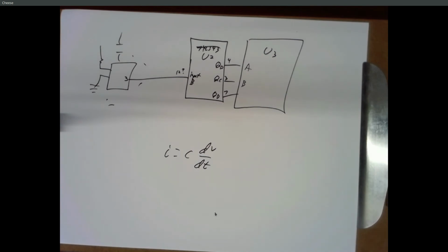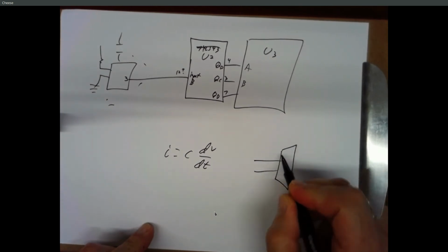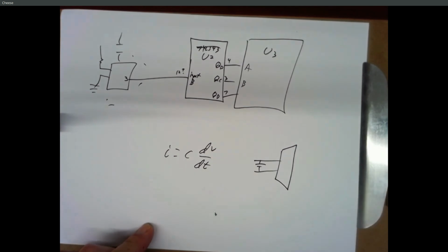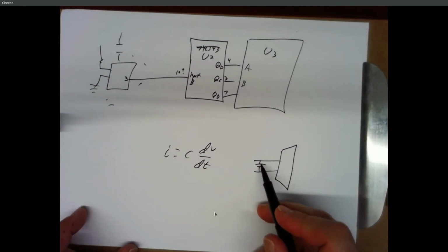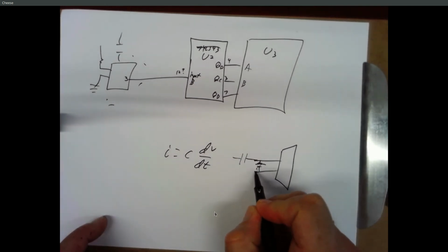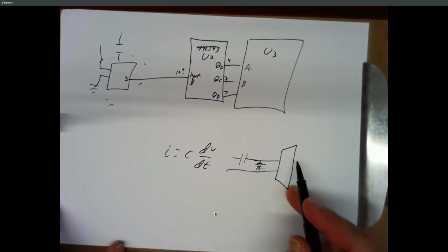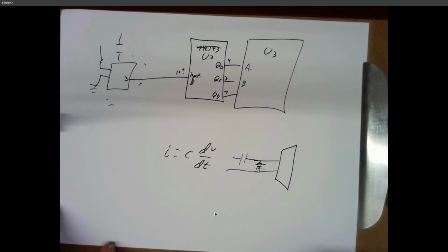You can make a really simple tone control on an amplifier, because if you short 2 lines going to a speaker, any high frequencies are going to get shorted from here to here. They're not going to come out, so you're going to bring out the bass. If you put it in series, any low frequencies are going to get blocked, and the high frequencies are going to come through, so it's like turning up the treble. So when I was a kid, my dad made me a little speaker system and had like basic tone control just using a few capacitors. It was like really exciting.